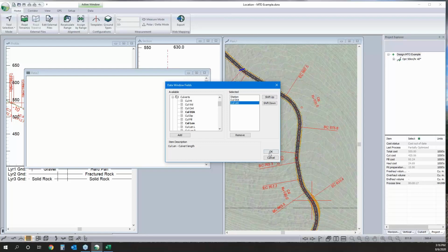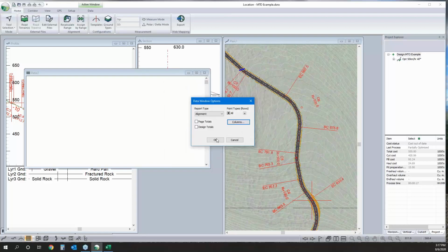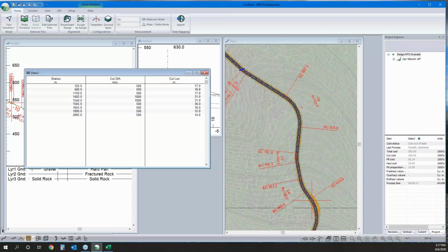And we'll also care about couplers. But if we go through here, we'll notice that there isn't an option to include couplers. So we're going to write our own attribute for that. We've got that. There's our culverts. Now we'll assume that whether we require a coupler and the quantity is going to be defined by the length of our pipe. So in here, we're going to go to attributes, and we have an option to add something new. So let's call this coupler. Heading will be coupler, and description, number of couplers.